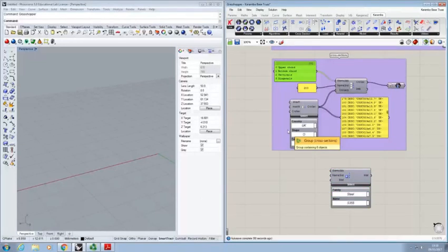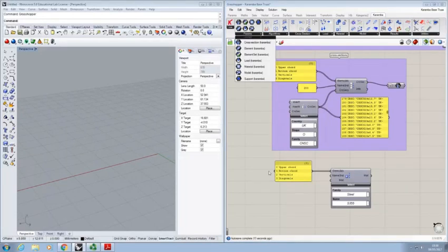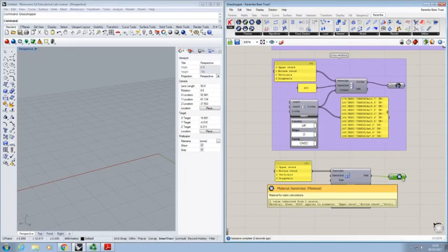So we can just copy this panel up there once with our 4 different material setups. So that applies S355 to the 4 different materials, and then we can assemble parameters, material. No need to flatten the list, there's only one item in that list.